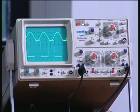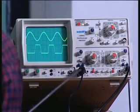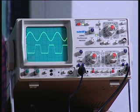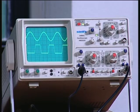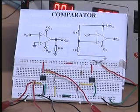Now you see this is better, now you are able to see the thing. So you can see the voltage is now in the 10 position, so it is about 20, the amplitude is 20, plus or minus 11 or 10, and therefore it is about 20 volts peak to peak. So this is again another example of how a comparator can be used for getting a sine wave converted into a square wave.